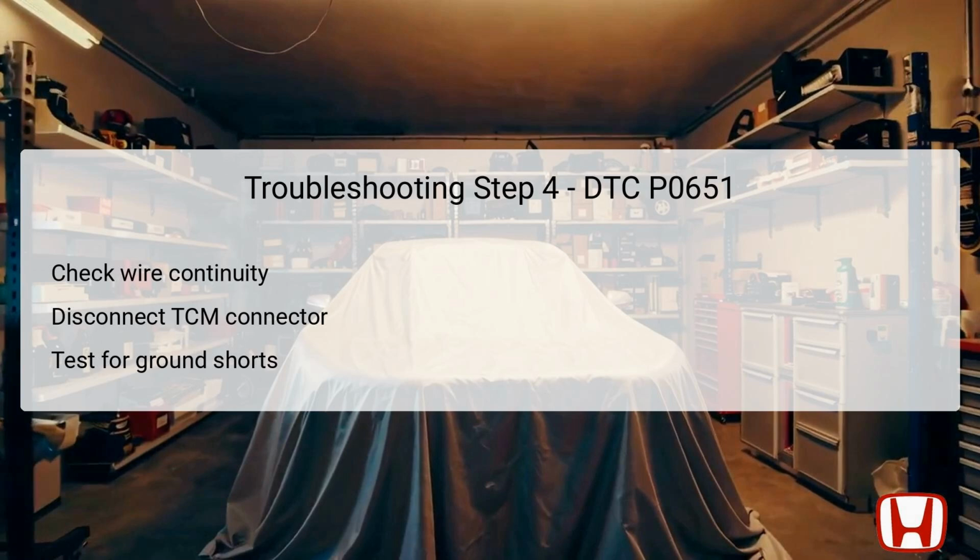The test points include the CVT speed sensors 3P, the torque converter turbine speed sensors 3P connector, and the TCM's 50P connector. If continuity is found when testing against body ground, this indicates that there is a short circuit in the VCC wire leading to that sensor. Repairs of the affected wiring are necessary to restore the proper circuit function.